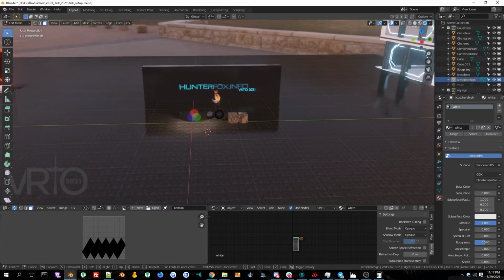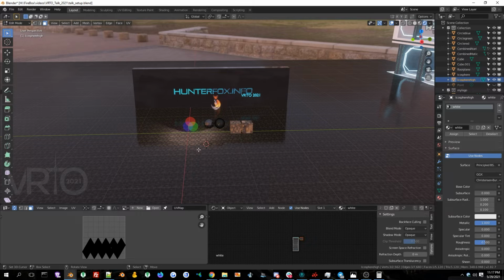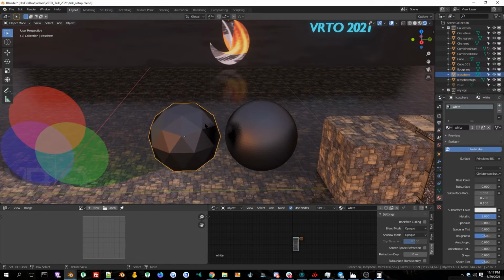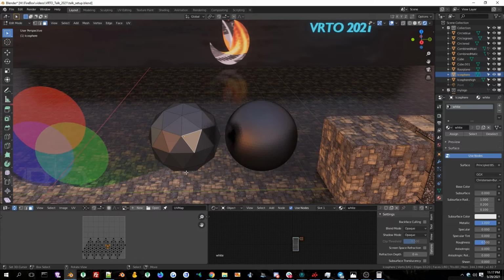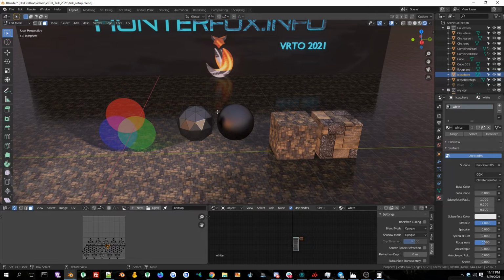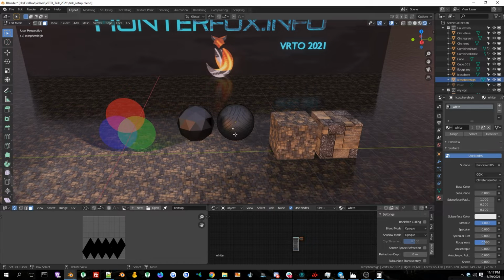This would be way too high a poly for this thing at this distance, because each one of these texels is smaller than a pixel that you're rendering. So you want to avoid that. Wherever you can, go with larger texels for your models. That's a big help for performance. It's just the way your GPU renders this stuff. It's very difficult for it to sort which one of these it's actually going to show at a distance.